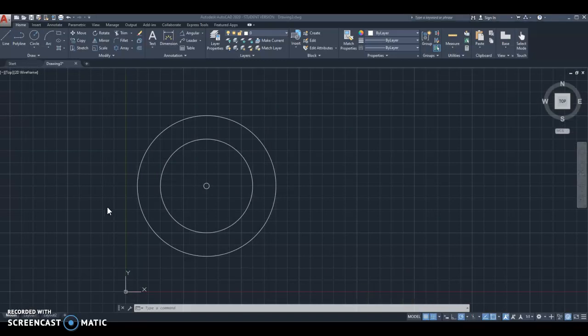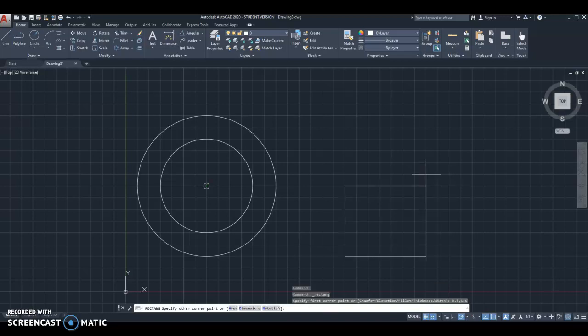Now we can start on the side view, and again, it's not typical for most drawings throughout the semester, but in this particular drawing, we are given the starting point for the center of the circle, as well as the starting point for the bottom left corner of the side view. It tells us to start at the coordinates 9.5, comma 1.5. So I just key that in with the keyboard, and now I can choose the opposite corner of my rectangle, the upper right corner. I can see by looking at the drawing that it has a width of 1.5.